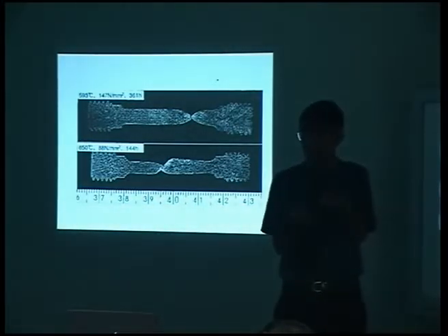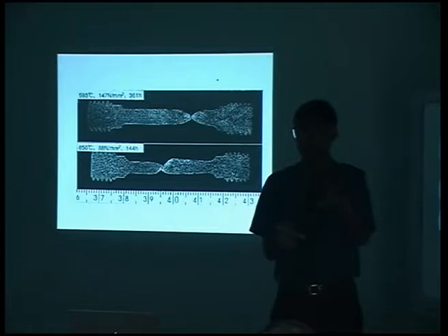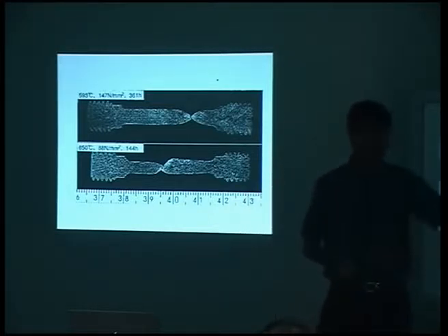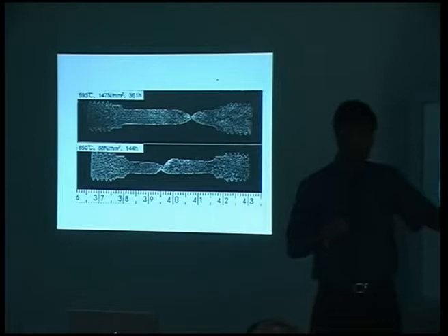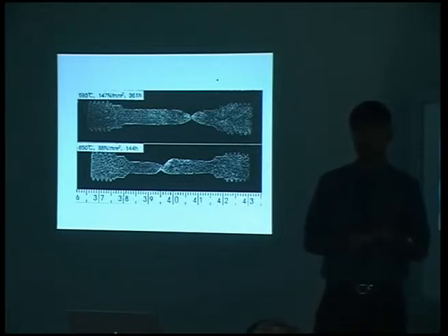So they've reported all the experimental data, the heat treatments, the chemical compositions, and the rupture stress, when you get type 4 failure and when you get failure in the parent. For the parent, we ought to be able to predict things accurately. For this, we should find a shortfall. That means the stress that we predict will be higher than the actual stress at which fracture happens.